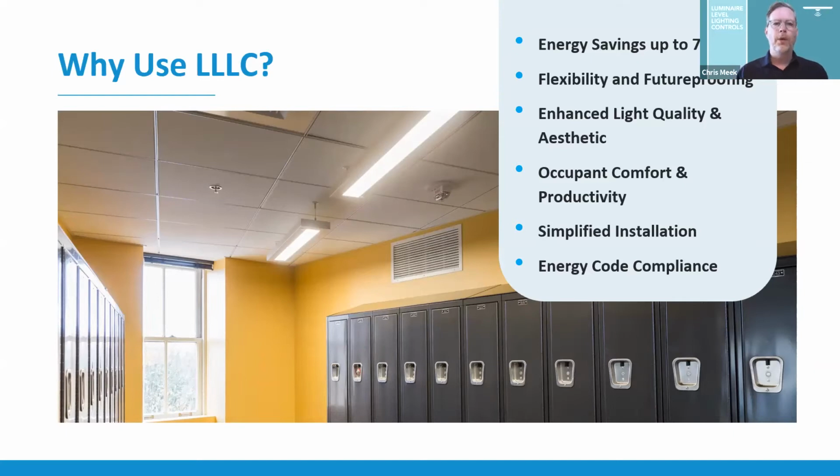Thanks, Chris. So why would we want to use luminaire level lighting controls? One of the primary drivers that we see is improved energy efficiency. We see energy savings up to 75%. That's from both the increased granularity of sensing and responding to spaces, and also from the customization capabilities, as Chris mentioned, with the high-end trim function. We also see their use because of interest in being able to reconfigure and reprogram the lighting system without having to add new control wiring, if you are configuring a space and you want flexibility and, quote unquote, future proofing.